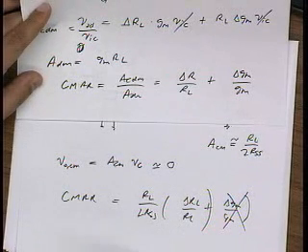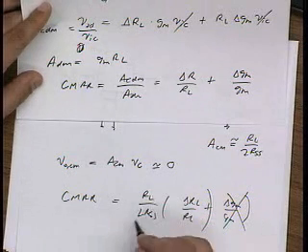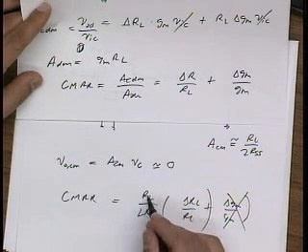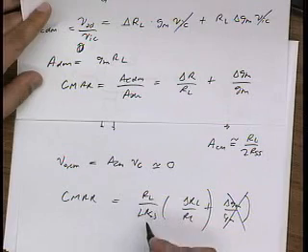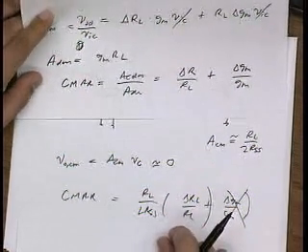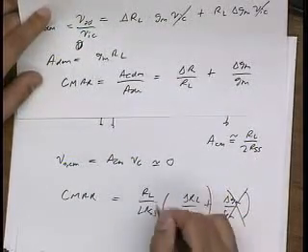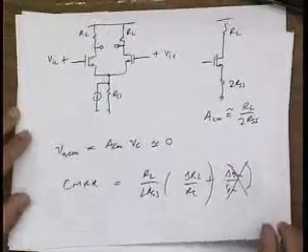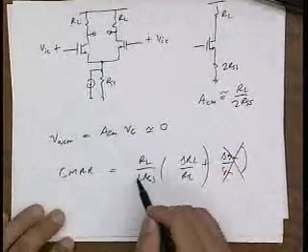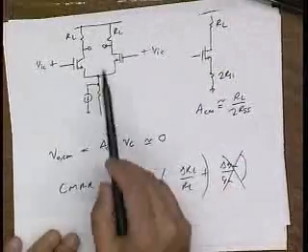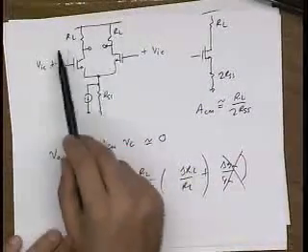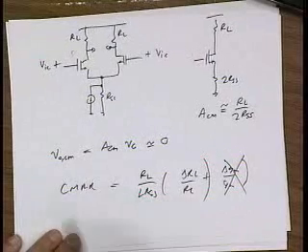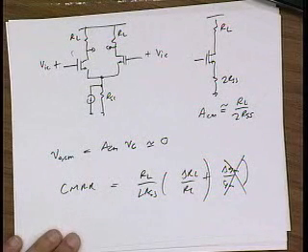Okay, so now you could see that if RL is a few kilo ohms and this is 10 mega ohms, clearly it's going to add a factor of 20 to 40 dB, right? I can easily muster another 20, 40 dB of improvement here. Now, of course, you might argue that, wait a minute, what if I have an active load, right? In which case, these resistances would be on the same order of magnitude, right? What saves me?